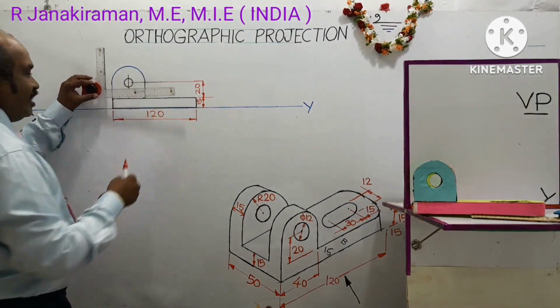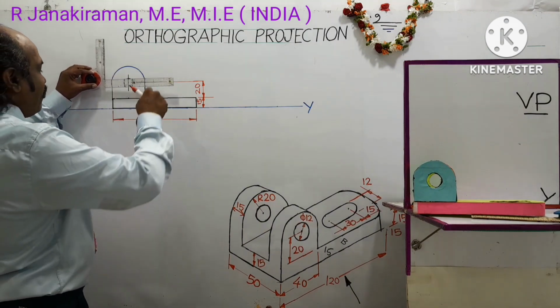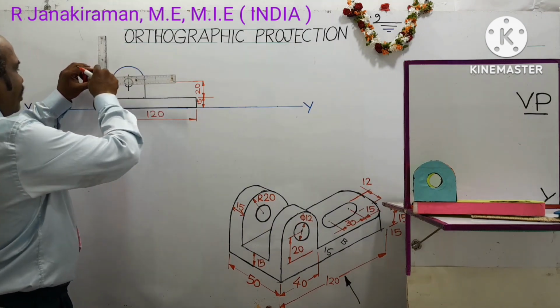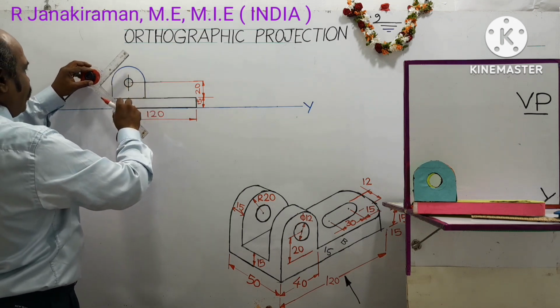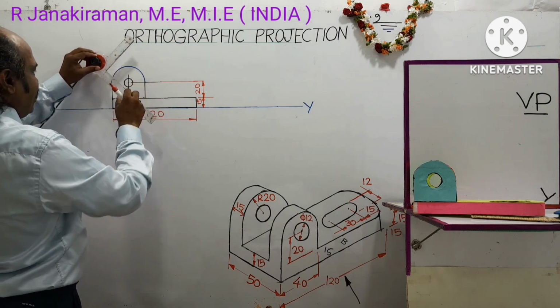So now I am going to draw the leader line. A leader line is a line inclined at 45 degrees. Release your drafter scale, rotate the nut anti-clockwise, and the scale will be released to set an angle of 45 degrees. This leader line is drawn.